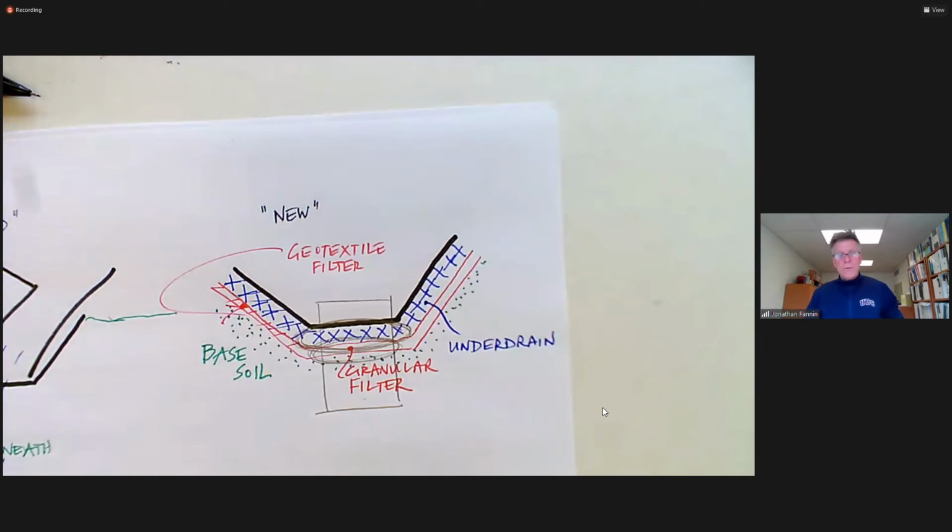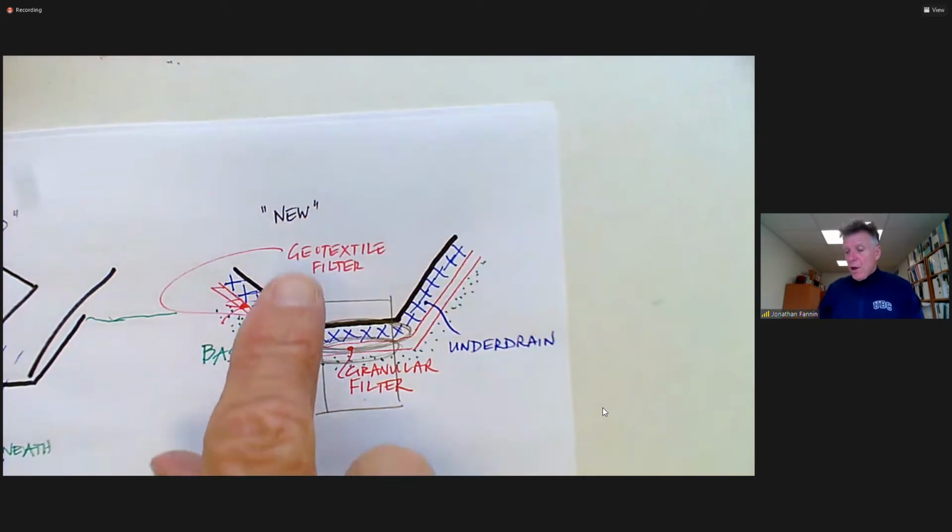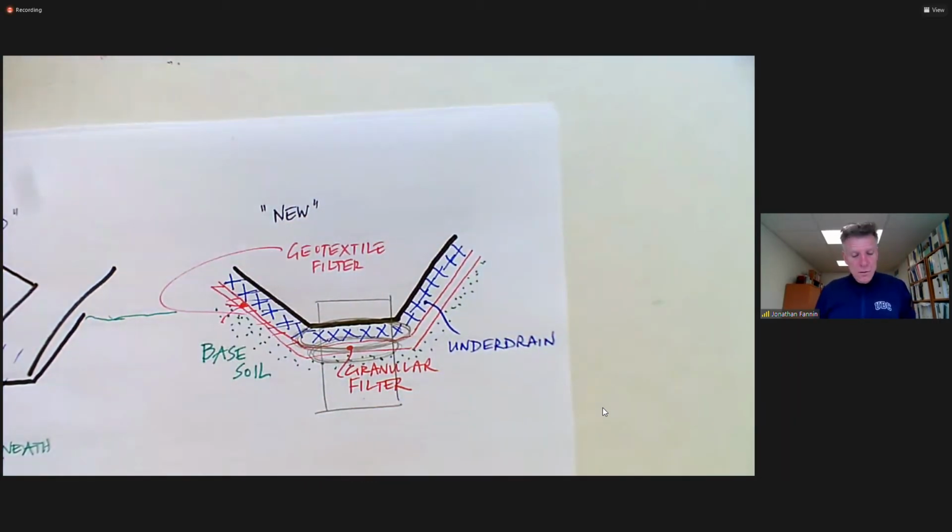And it's uncommon for geotextile filters to be used in dam engineering. Dam owners tend not to like geosynthetics, unless they're in areas of the dam that can be accessed and rehabilitated. It's relatively new, although that's a weak descriptor these days, because geosynthetics has been around for some 50 odd years now. I think it's more that if we can do it with sands and gravels, we will. So the question was, can we do this with a geotextile filter?